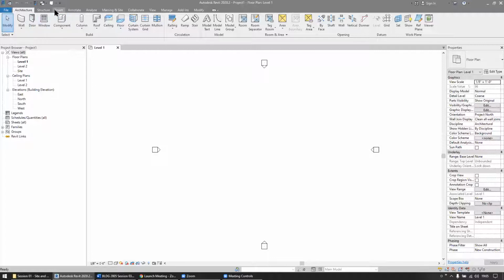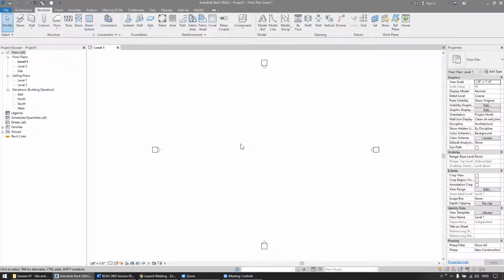Revit has a good set of structural modeling tools, and one of the advantages for a structural engineer using Revit for design is that, of course, they have a 3D model not only for coordination purposes, but also because there are structural engineering analysis platforms out there that will accept a Revit model, and they will do various structural analyses of the Revit model, including seismic.